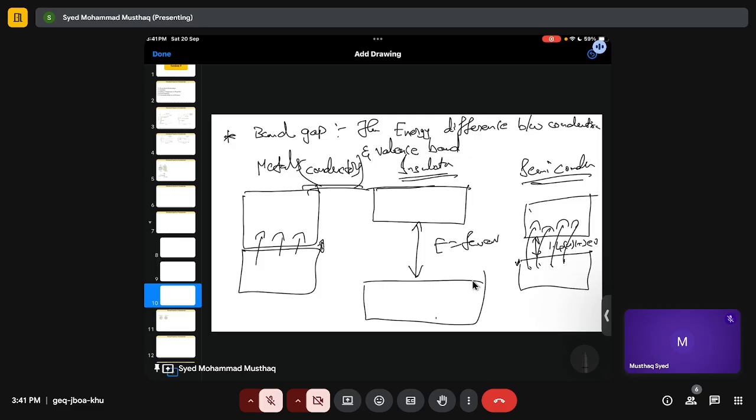So that's how it is. For this, the resistivity versus temperature is the best way to define the difference between conductors and semiconductors. If the resistivity increases with temperature, then you call them conductors, and if the resistivity goes down initially with the temperature, you call them semiconductors.